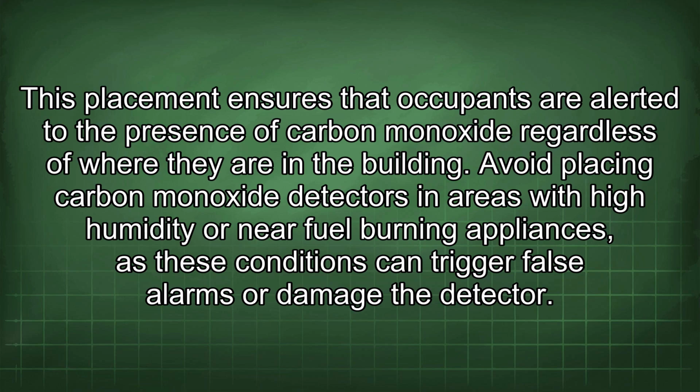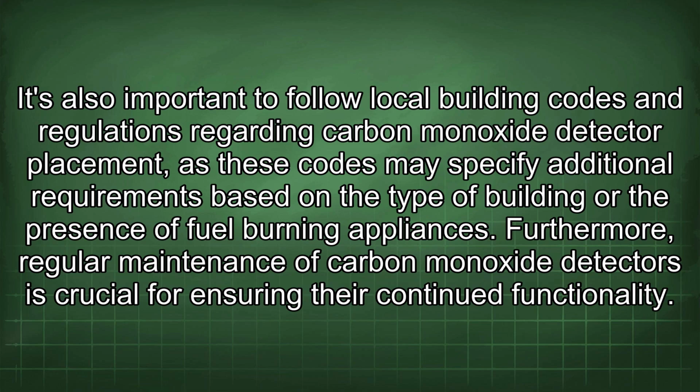Avoid placing carbon monoxide detectors in areas with high humidity or near fuel-burning appliances, as these conditions can trigger false alarms or damage the detector. It's also important to follow local building codes and regulations regarding carbon monoxide detector placement, as these codes may specify additional requirements based on the type of building or the presence of fuel-burning appliances.